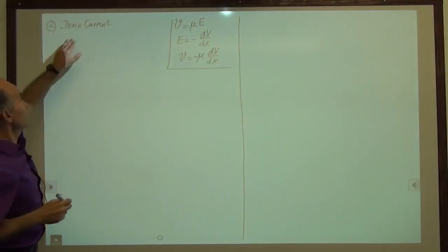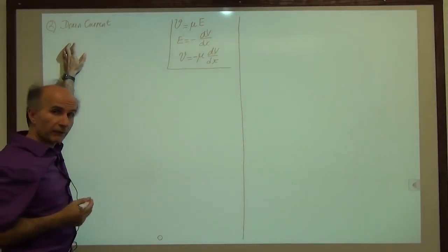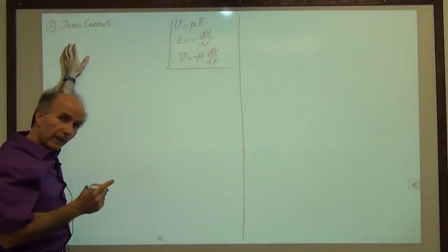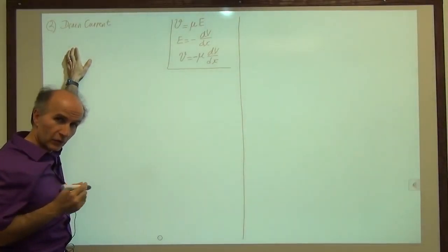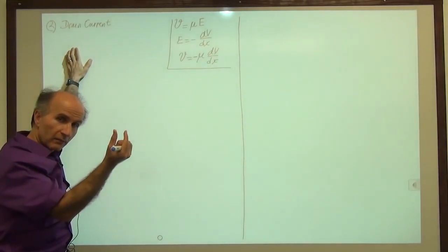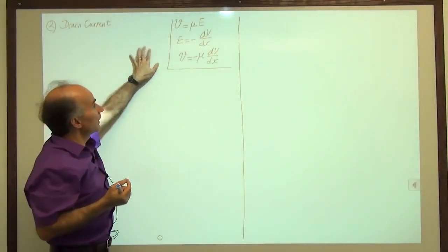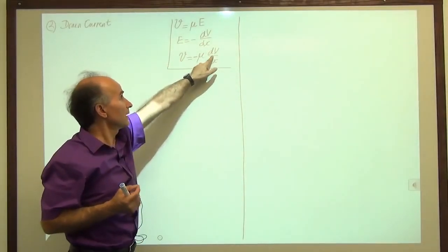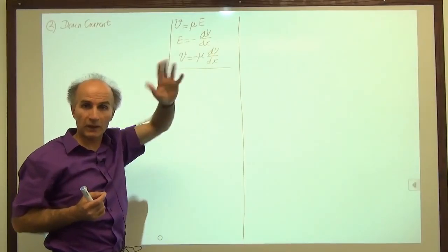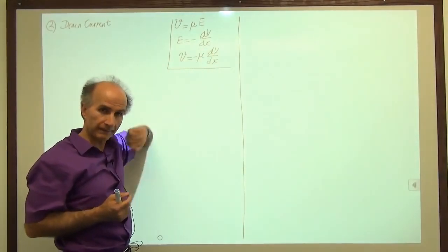Okay, so my objective is to find the drain current. And I have found the following. On the previous page, I found the charge density in the channel, the charge for 1 meter of length. Here, I have found the velocity of the carriers in terms of some internal voltage V: dV over dx times mu times minus 1 is v.